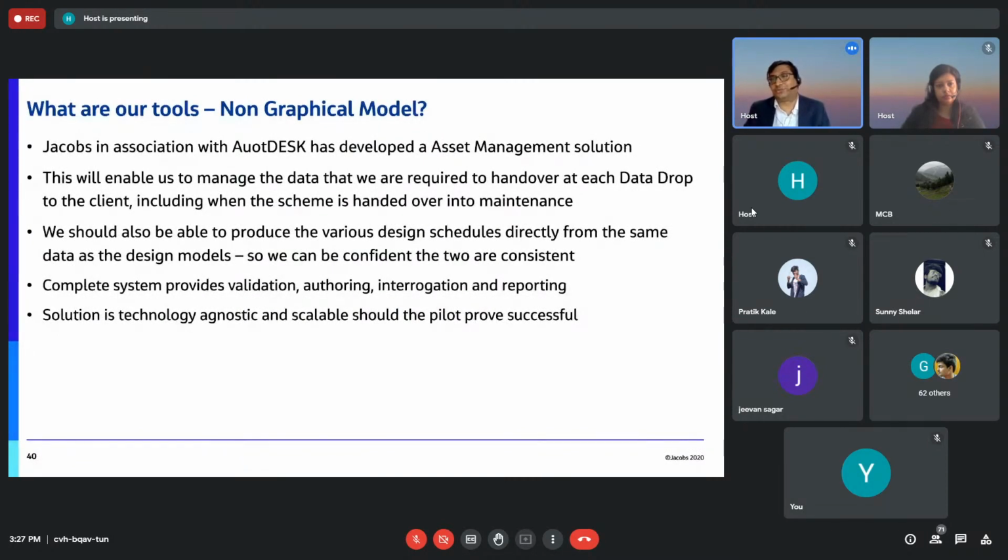The luminaire of the bulb will be specified and designed, so you cannot just fit in a low luminaire bulb, otherwise the lighting won't work. So we build the asset information into that element of design. When the contractor or the maintainer goes to the field, he can check the federated model in the office itself and understand the luminaire of the bulb he needs to replace.